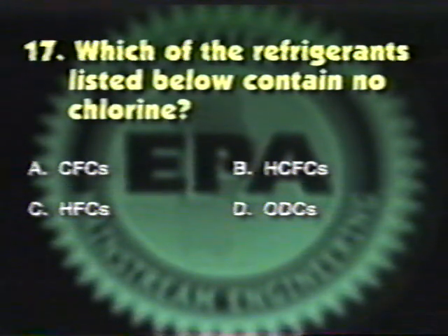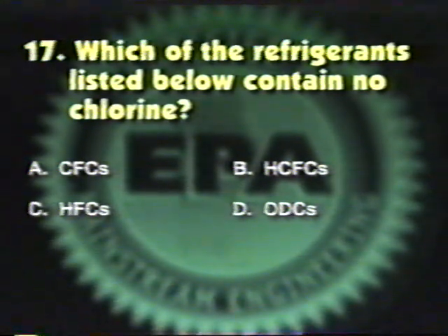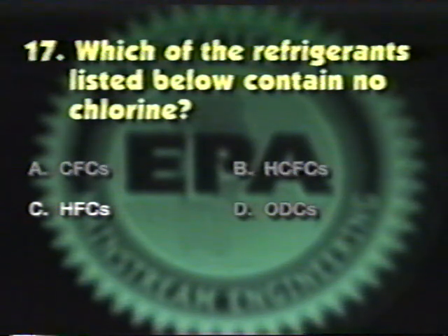Which of the refrigerants listed below contain no chlorine? A. CFCs, B. HCFCs, C. HFCs, D. ODCs. The answer is C. Hydrofluorocarbon, or HFC, refrigerants are chlorine-free. They contain hydrogen, fluorine, and carbon.